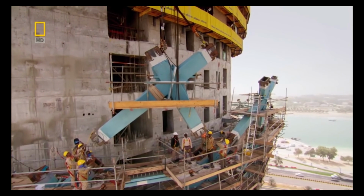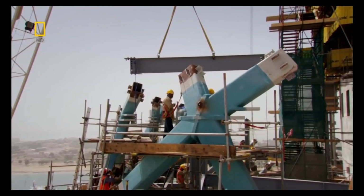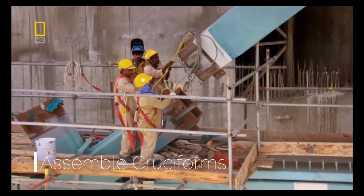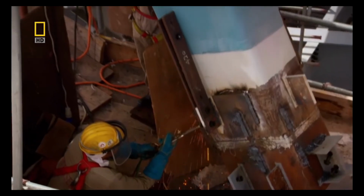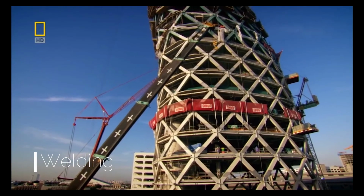The location of the center of gravity and weight of individual parts were used to work out the lifting method and in the design of erection engineering. When it was lifted to the precise angle to match the opposite side of the endpoint, a team of 240 steel fabricators assembled the diagrid with the node and welded all three together.